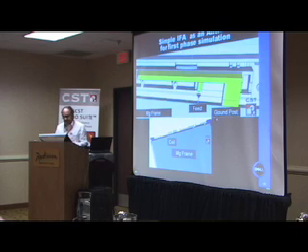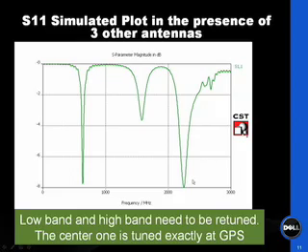So this antenna was simulated after assigning the material properties from the CST database. Of course you can also measure your own property, but what I've observed is that the material database in CST is pretty close to what is available in the standard literature. So you can as well take the material property from the database and assign it.